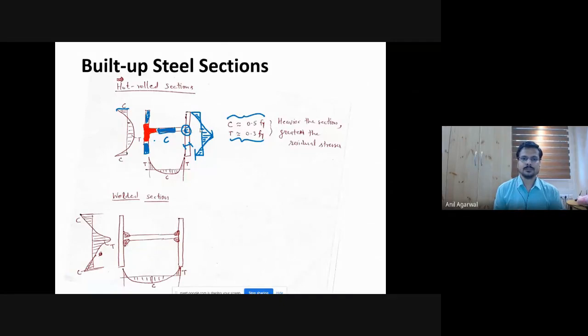Okay. Good. So the same thing. And of course, they have to balance each other because that force is not coming from outside. That force, the red part is applying on the blue part. So the two have to manage between them. The two forces have to balance, so total compression has to be equal to total tension. But maximum compression need not be equal to maximum tension; that depends on the way it is distributed. If it is distributed like this, then this compression force may be higher than the tension force. If it is distributed like this, then maybe the maximum values are also the same.